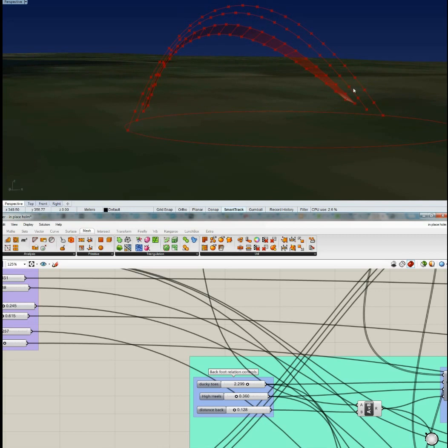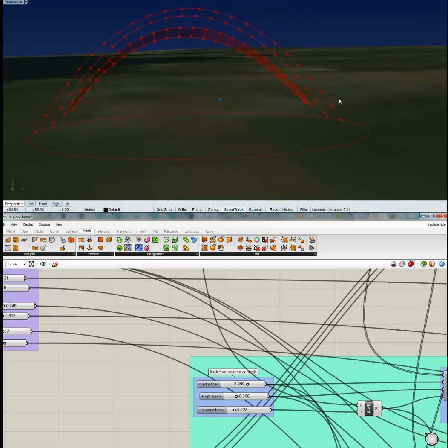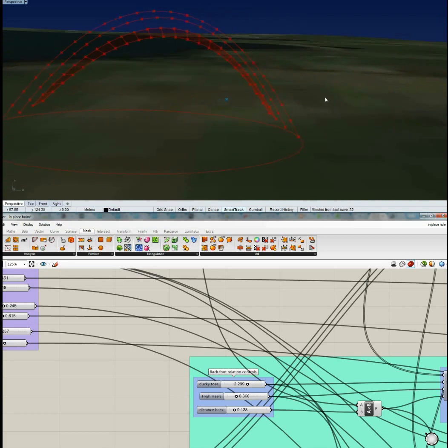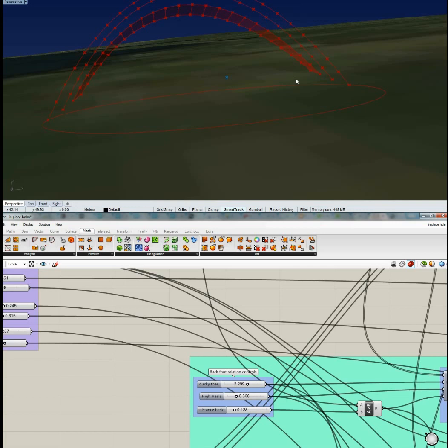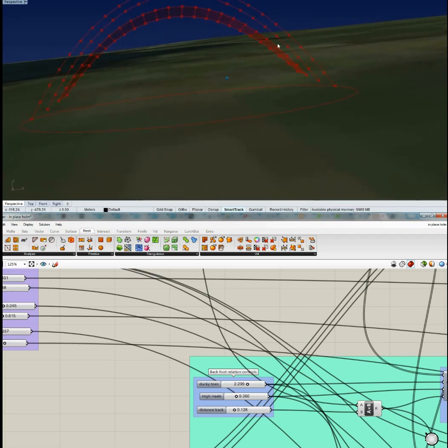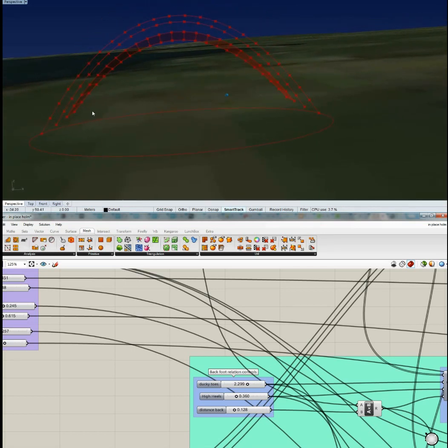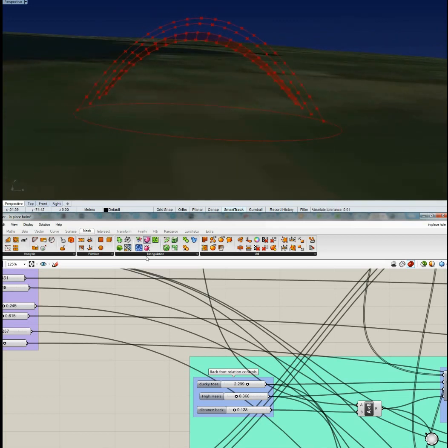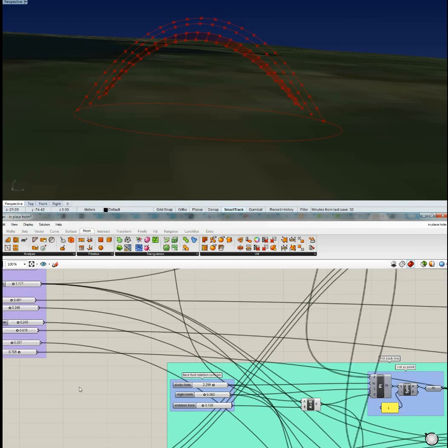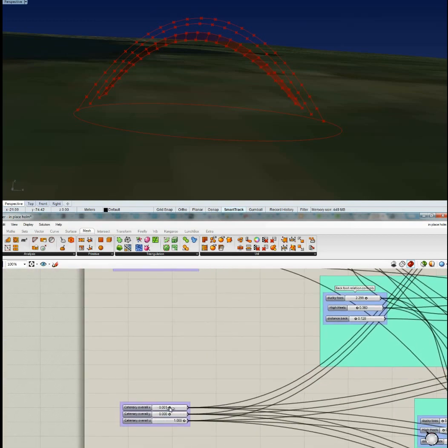This is obviously a very efficient form, an arch, a catenary set of arches, tying between them, as you've got the lift and drag function all built in, and it has inherent stability due to the side forms always wanting to weather vane, weathercock, so that if it did blow off to the right, say like that, then this side is going to want to drive up into the arch because of the lift generated here.